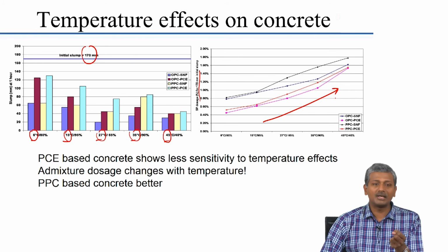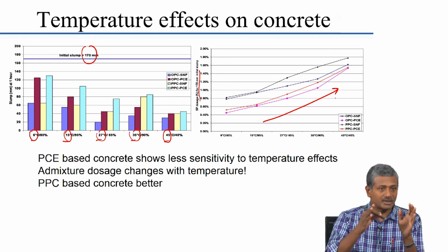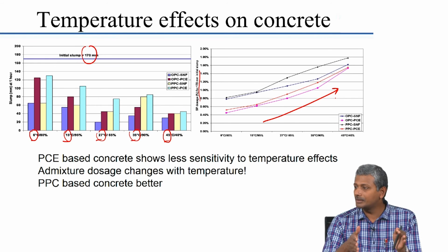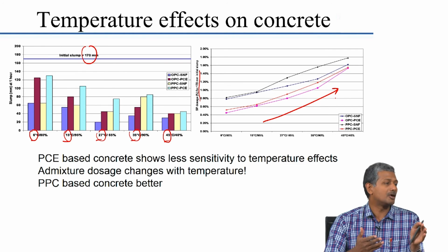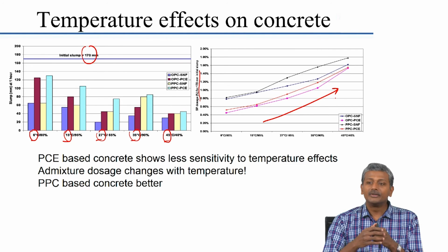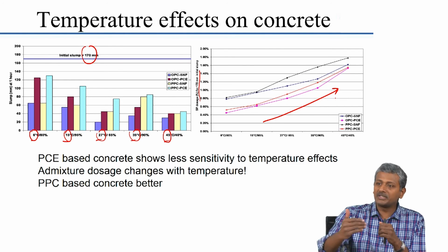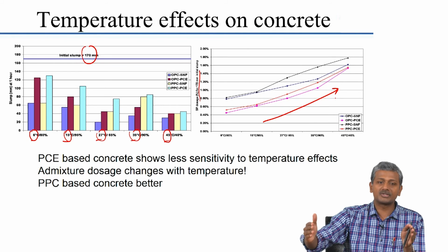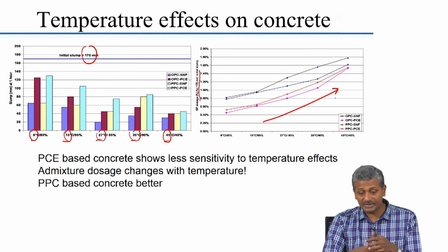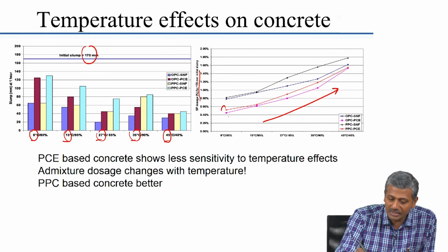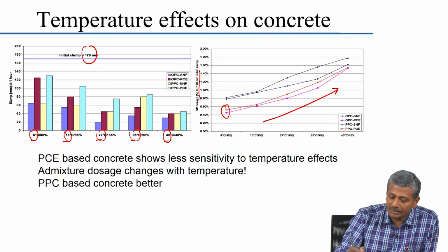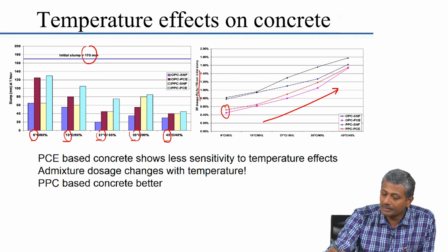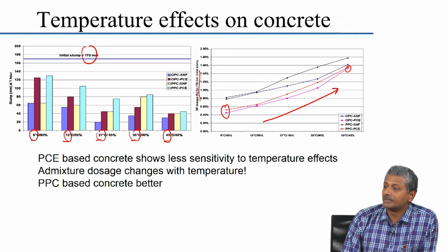Now, very often when you are dealing with government clients, they want everything written very clearly. So, when you do your mix design for these projects which are involving government clients, you need to ensure that you specify what could be the range of superplasticizer dosages that are permissible in this concrete. For example, for this concrete mix, you see that for 6 degrees Celsius we are down at about 0.4% for, let us say, this pink line here, 0.4%, and here we are up at about 1.5%.